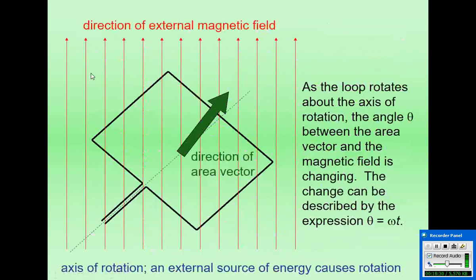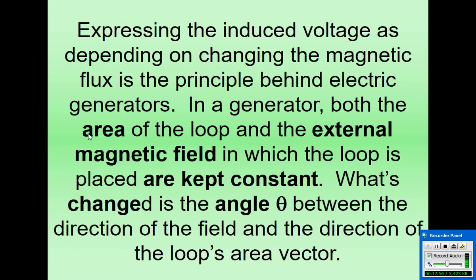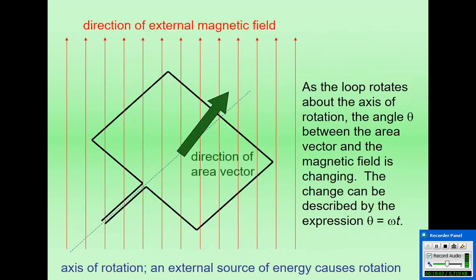If we examine that a little more closely, we imagine a rectangular loop in a magnetic field. Now, this rectangular loop is intended to be a three-dimensional construct. You can imagine the external magnetic field pointing uniformly up, and you can imagine the loop perhaps being shaped like a pizza spatula, one of those big rectangular pizza spatulas with a handle. And you can imagine that being perpendicular, or in the third dimension, if you will. And what we do is we rotate it around. Imagine putting that pizza spatula in the oven and somehow twisting the handle around so that the blades, if you will, of that spatula start rotating around. And that's more or less what's happening. Except obviously it's not in a pizza oven.